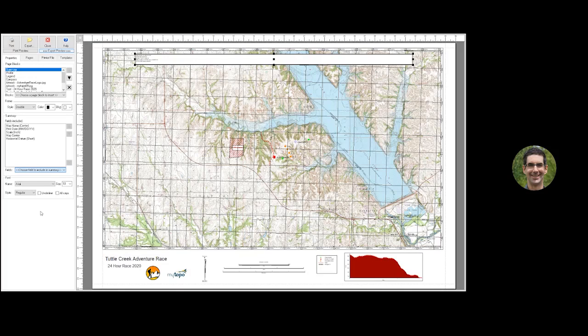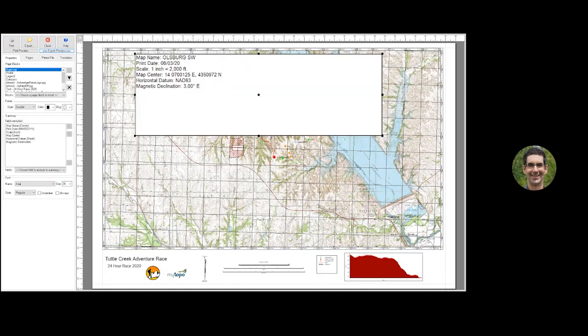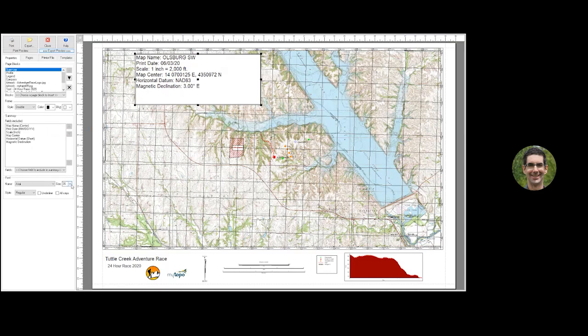Yeah, I mean, there are options here. So you have a magnetic declination option. This little summary tab is going to show you, let me make the text size larger here. It's Terrain Navigator Pro, so everything is customizable. But you can show different things on there, like what's the magnetic declination, what's the scale here, and so on. And all these are available just based on what you put here. So that's a summary page block. So yes, that is an option.